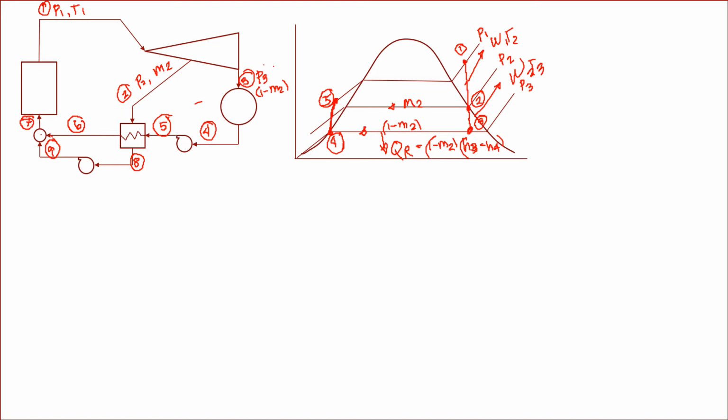Okay, now there's a pump application also here. And we notice we go down to the condensate. This is your 0.8 here. Okay, the steam that is coming into the closed feed water heater has been condensed and is still mass M2. Of course this is mass M2. This is 1 minus M2. Here it goes inside the pump and is still 1 minus M2. It goes out of the closed feed water heater but still 1 minus M2. In the later part, at the junction it is joined with M2, so it becomes 1.